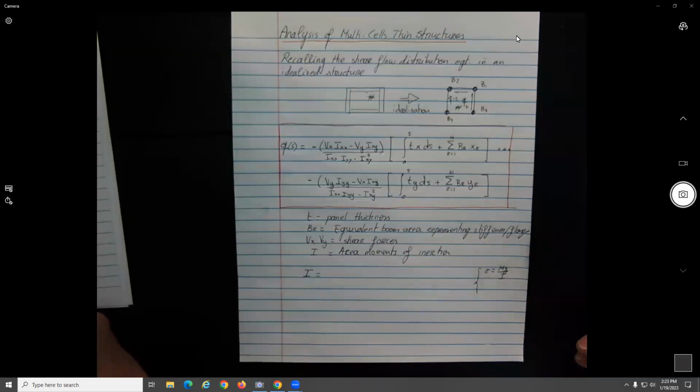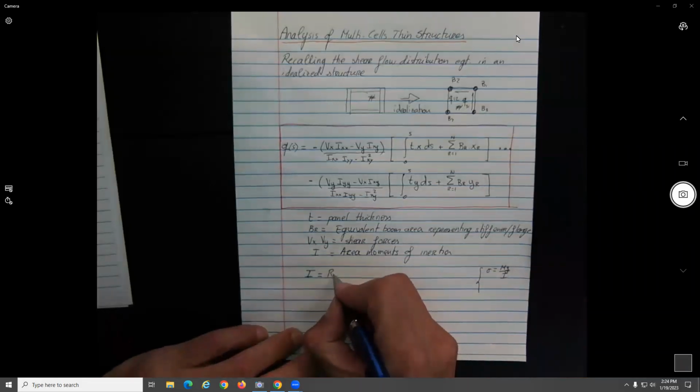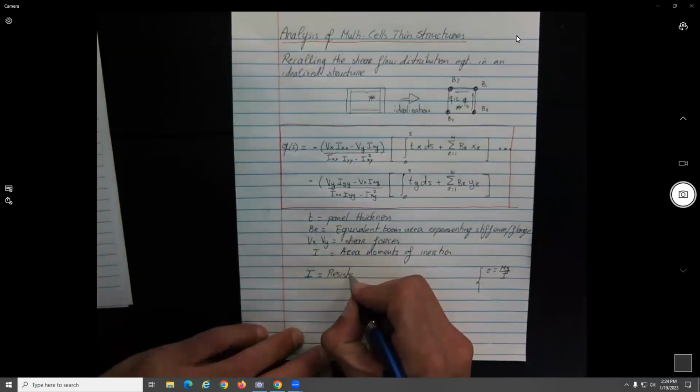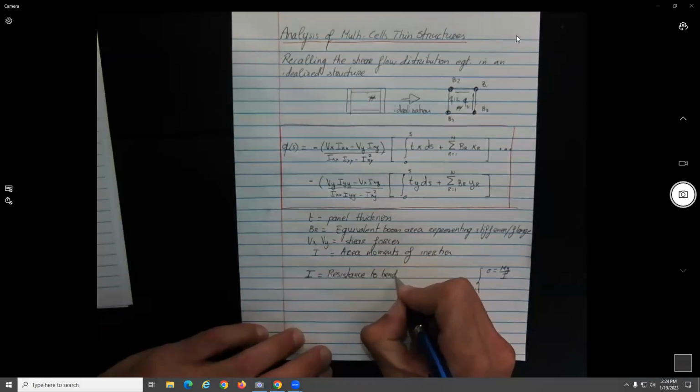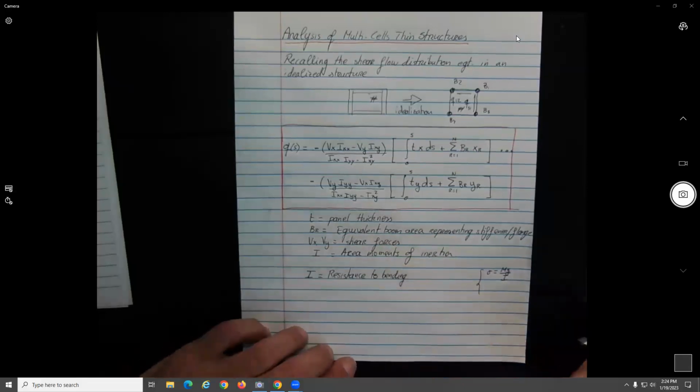Yeah, about that axis. That's changing. So is it bending or shearing? I think you were asking for I in general. Yes. What is I in general? It's resistance to change. Okay, but it's resistance, so I agree with that one. It is resistant to change, not that much to change, but to bending or to rotate about one axis.